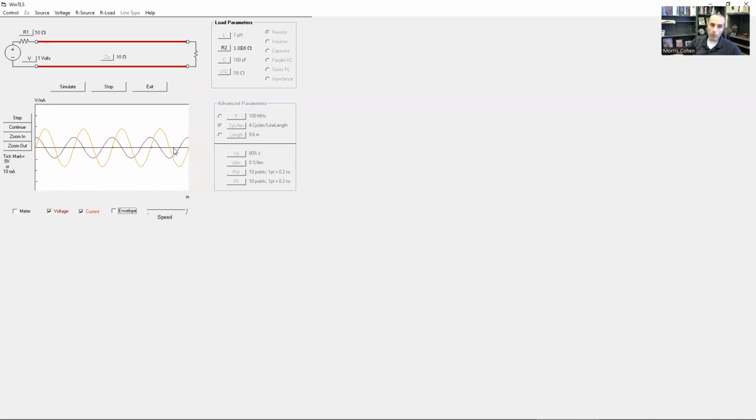If we move to the quarter wavelength point, right where my mouse is right now, here we've got no voltage change, but you've got the current changing by a big amount. So the current and voltage are also off by 90 degrees with respect to each other. And again, this is the voltage and current that represents the sum of a positive going voltage and current with a negative going voltage and current. Those sum up to create this standing wave pattern, or a bouncing up and down wave that does not seem to be moving.